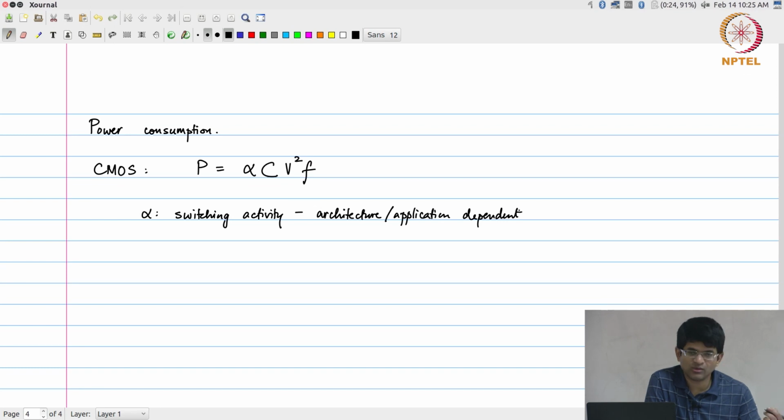Okay. In general, what happens is that in a large circuit, you can expect that at any given clock cycle, roughly 10 to 20% of the wires are going to switch their values from 0 to 1 or 1 to 0. And a fundamental thing as far as CMOS circuits is concerned is the predominant consumption of power happens only when there is actually switching activity, when a given wire is switching from 0 to 1 or from 1 to 0. Okay. Some current is required in order to charge that output capacitance or discharge it, and that causes a dissipation of power, of energy.